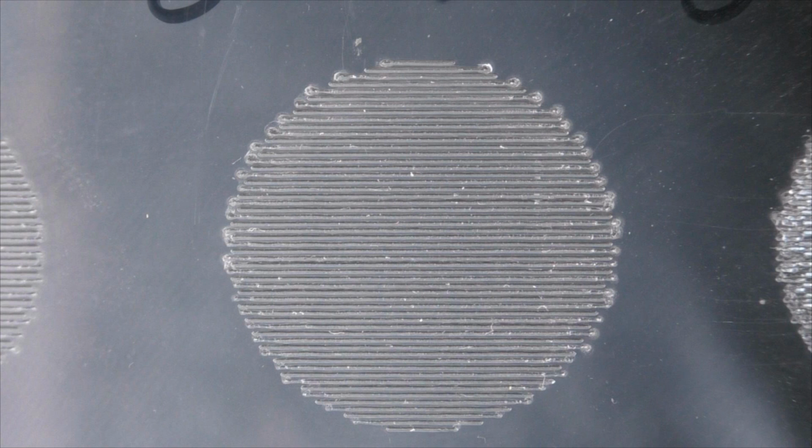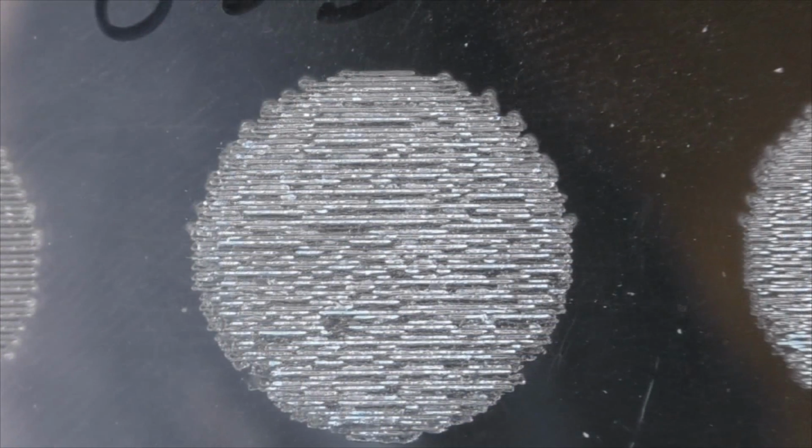Okay, I hear you say, well, we'll just move the lines closer together. Yeah, it isn't quite as simple as that, because let's change the pitch now, the spacing, the interval, to 0.3. All of a sudden the software has become totally confused. It doesn't know whether to draw a line or not draw a line. There's all sorts of gaps, overlaps, strange things going on. That's 0.3, which is only a small error from the 0.4. Bearing in mind we're talking about millimeters, so that's only 0.004 of an inch difference in the pitch.